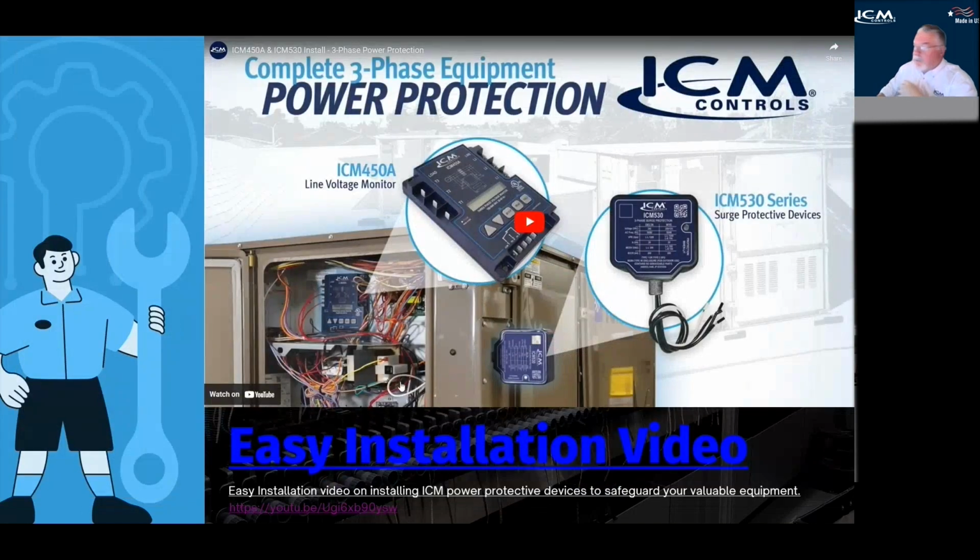Okay, so easy installation on both products. The reason that we married those together, if you're installing a three-phase line monitor, they do a great job at preventing the equipment from starting if the voltage is any of those conditions we looked at before. If the voltage is outside that range that you set, or if those other power anomalies occur.